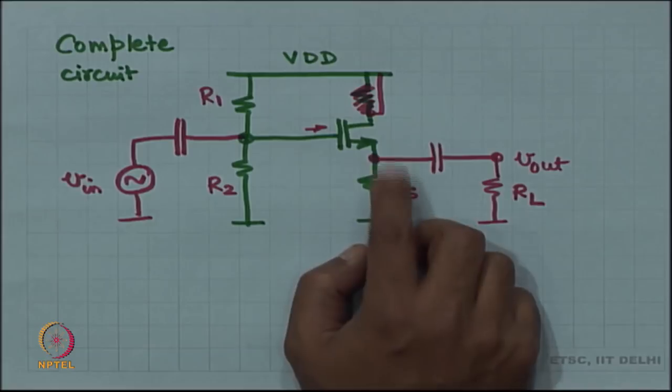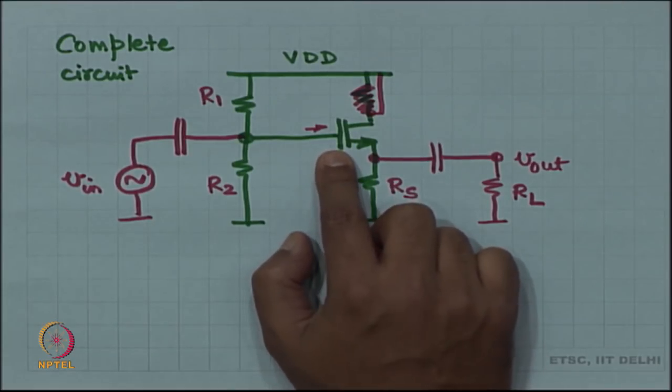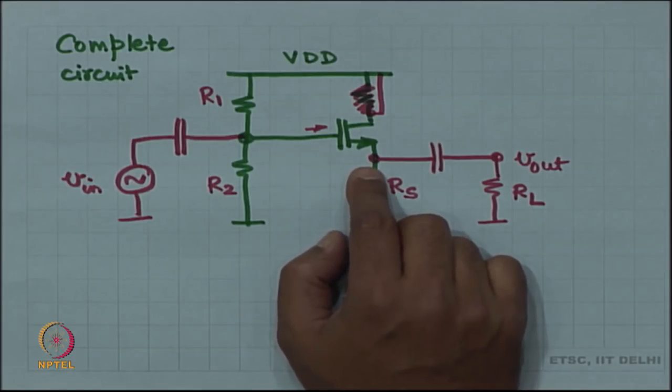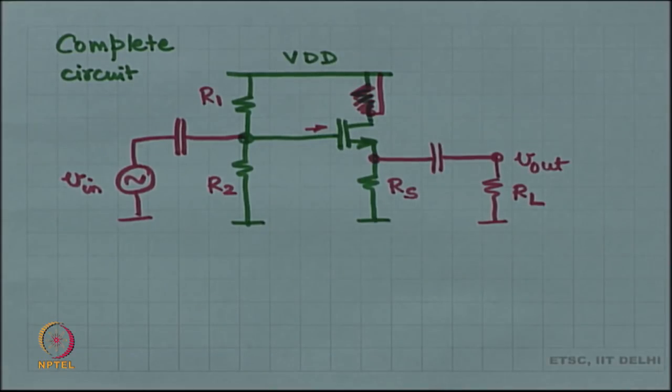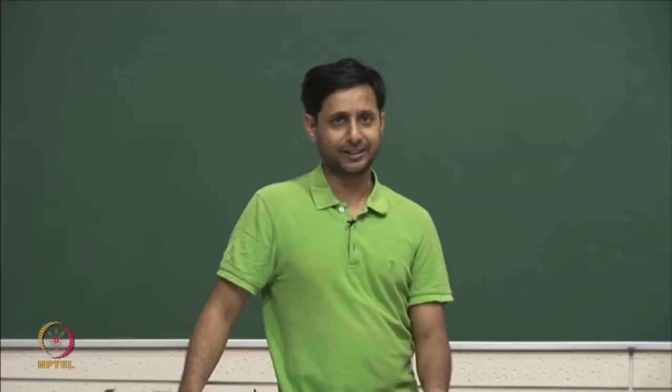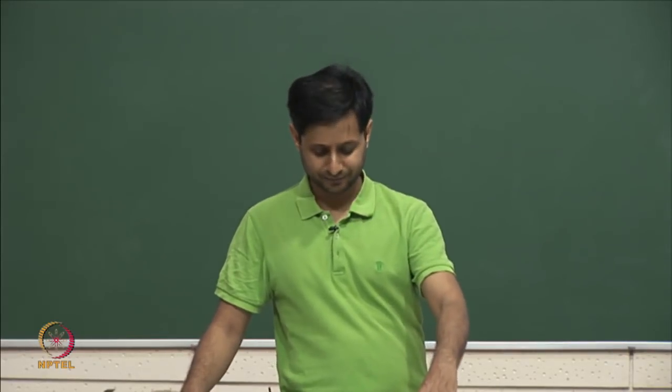right. Then you find the drain current, check what is VGS minus VT for this drain current, you are going to work out that oh, it was not 0.14, it is 0.142, and you are all set. Okay. So, 1 or 2 iterations at max, and you can figure out what is the exact drain current, you can establish the drain current, couple of iterations is good enough.